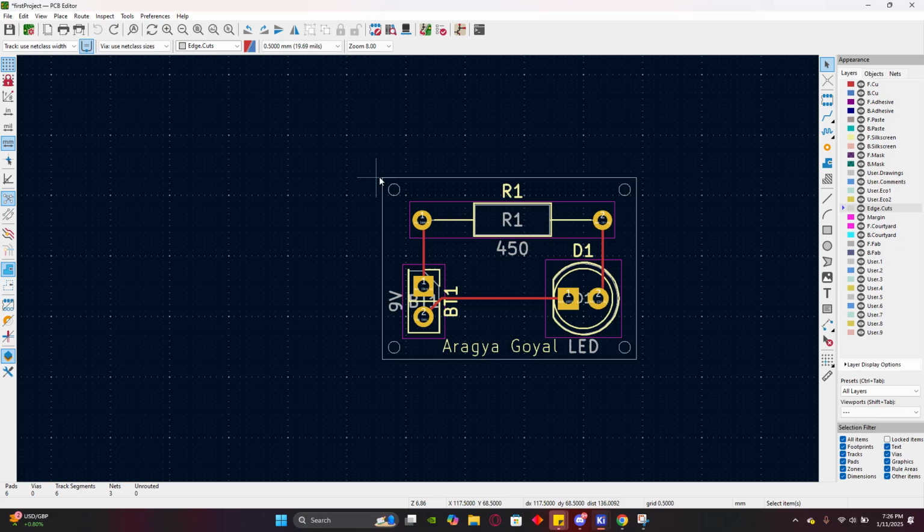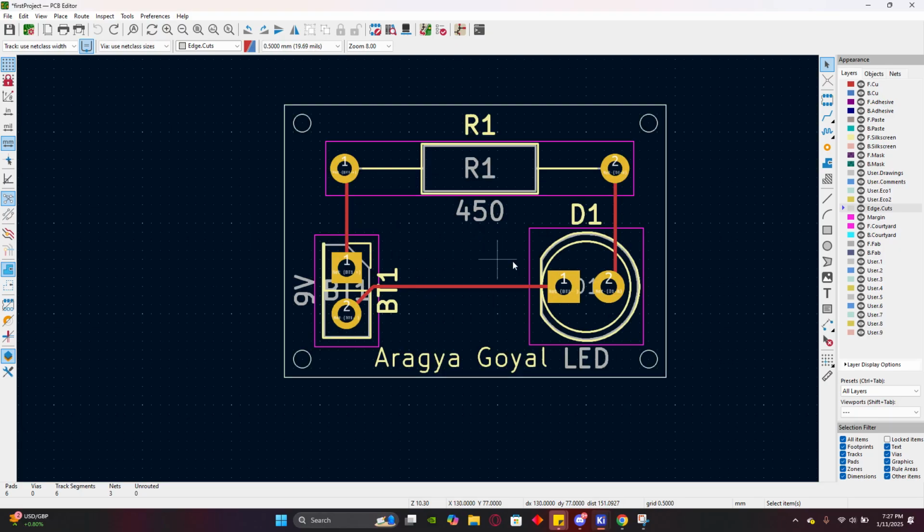I put it the way you did, but do I have to put separate lines for each of these, like the red lines? Yeah, the wires. To do that, you'll just go onto the front copper layer. Press on front copper layer, and what you can do is press this thing here, route tracks, or you can press X, which will do the same thing, and then it will show you ghost lines between them.